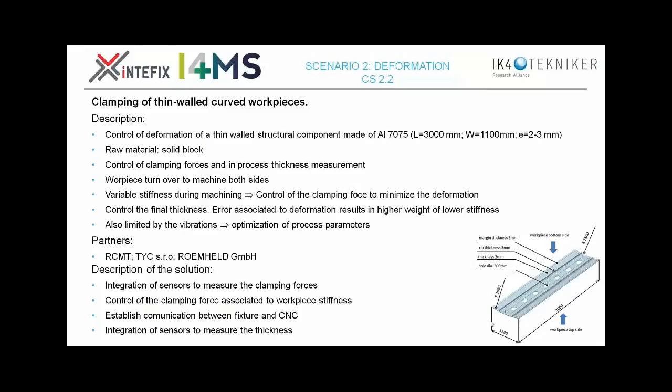And also in this case, it's important to integrate sensors to measure the resultant thickness in the final workpiece, because an excess of thickness means more weight in the aircraft, and a thickness lower than expected results in lower stiffness of the component, and possibly a failure of the component in use.